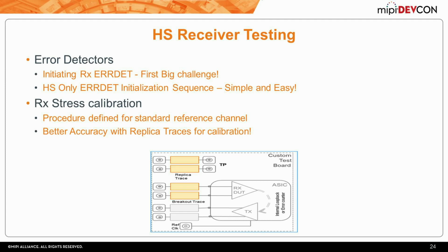Essentially, you connect your generator here. This trace exactly replicates what it has in your design, and you take this out and connect to the scope, okay? And then now you calibrate and get that eye. So after calibration, you feed this input to your design and test. So this would be more accurate and I think a more realistic data you would get out of this.